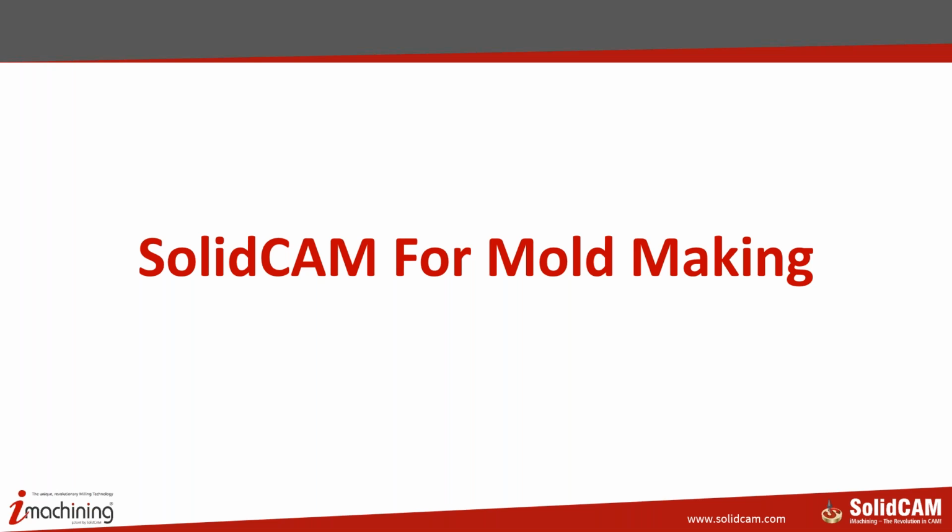We're going to put some changes into the main part, and we will see how the entire integrated system takes care of propagating these changes seamlessly right from the separation of core cavity being updated, electrodes being updated, the CAM being updated, the drawings being updated, how this is done completely in one process. So this is the process that we are going to look at.